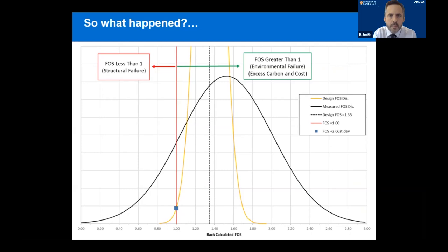I believe the main reason for this uncertainty is that our current mathematical models cannot accurately predict the load paths in statically indeterminate structures. This is most likely due to construction build sequences, and the connection and the bearing stiffnesses behavior in the models are actually different in reality. We need to get better at this. We need to do more monitoring with back analysis, and engineers need to get better at applying statistics.